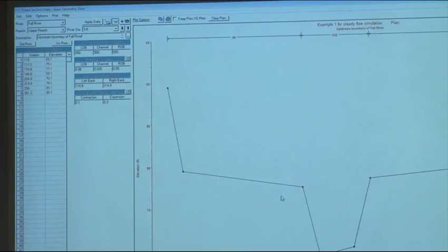Yep. Okay, I did not change the channel length for 9.9, but there's no changes. But for 9.8, we have to do some change. So the downstream reach length for the LOB, main channel, all will be 0.